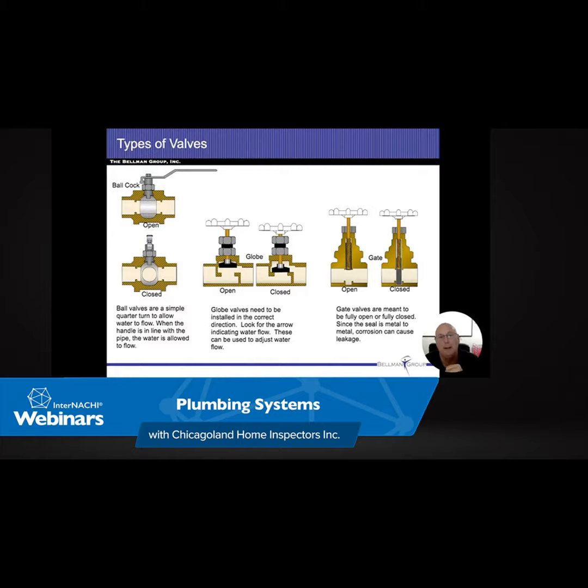I've seen it in one house where we had the double trap, and I swear that gurgling lasted for, I want to say, about a minute and a half. You just hear gurgle, stop, gurgle, stop, gurgle, stop. Now in this situation, because we have that sink in between there, that would probably stop the gurgling. But if that was filled with water and draining, that would get air being sucked into both of them, especially if the right side was empty. Then that would go ahead and gurgle.